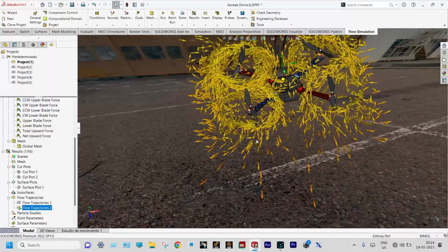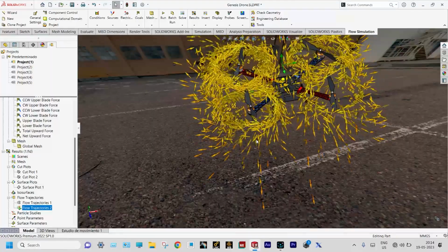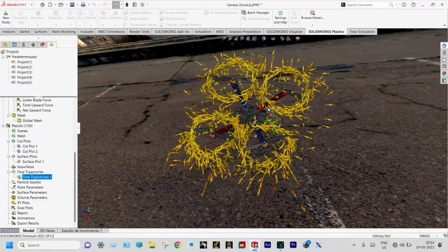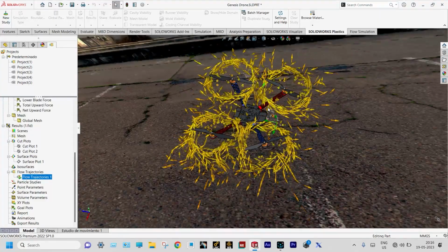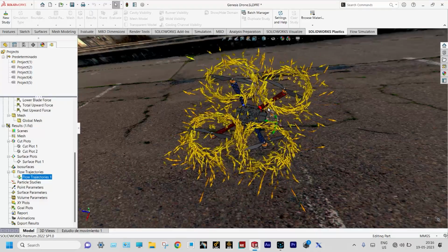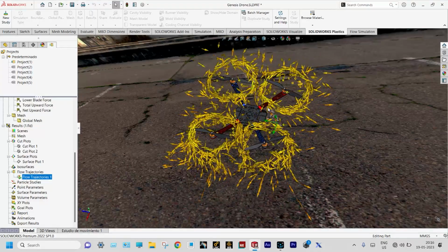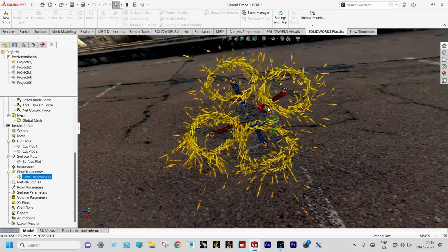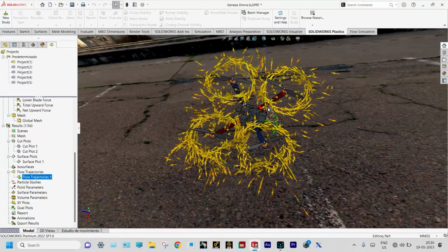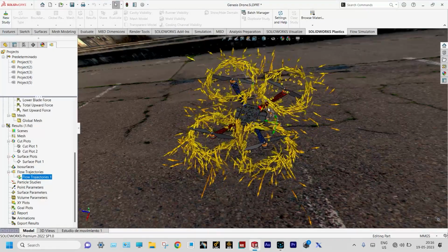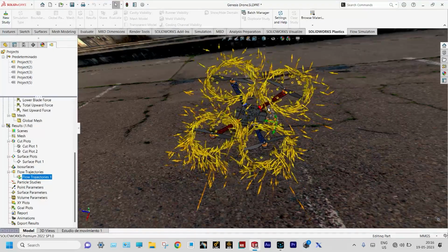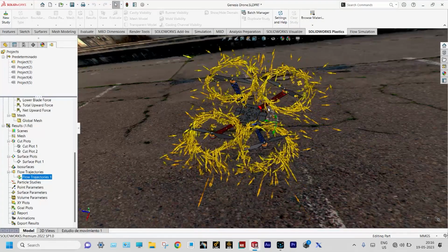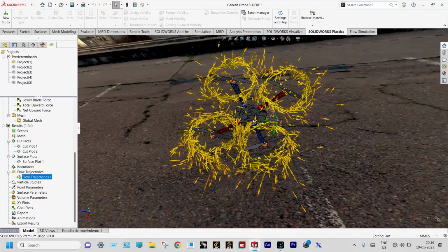So at the four centers of these propellers, some vortex motion is created. And from this one, we can see that thrust is not that much produced. We cannot see that much thrust is produced because fewer air particles are coming down. And those particles which are coming down, those are actually producing thrust. So in this case, thrust produced is not sufficient enough to move the drone in the upward direction. That one we'll see from the goal plots, right? So let us close this one.